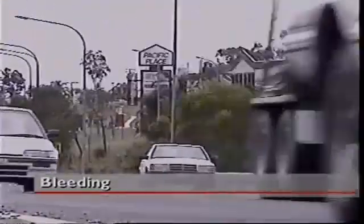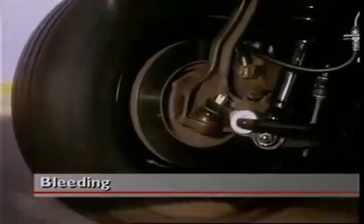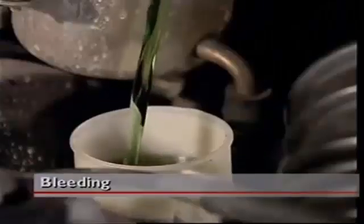That is why, if air enters a hydraulic braking system, it can be dangerous. Pressure on the brake pedal will not be transmitted in full through the system to apply the brakes. The brakes will be spongy. Bleeding the brakes means removing this air so that only liquid is left in the system.